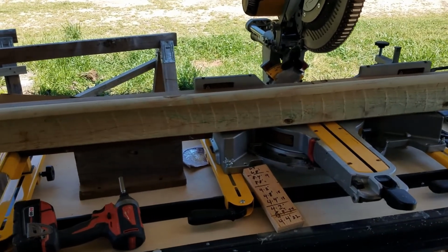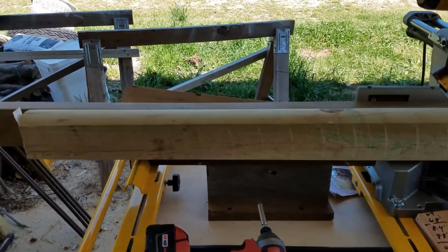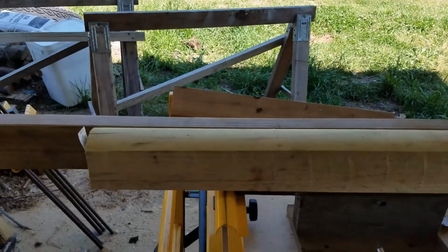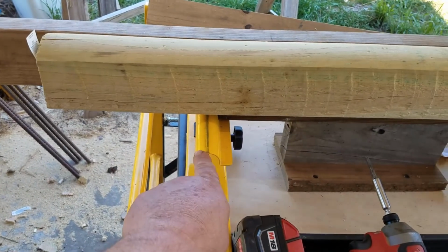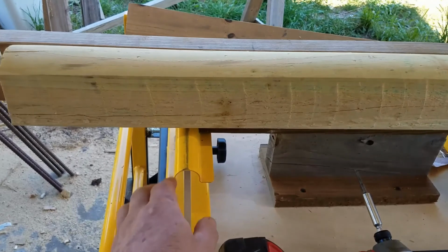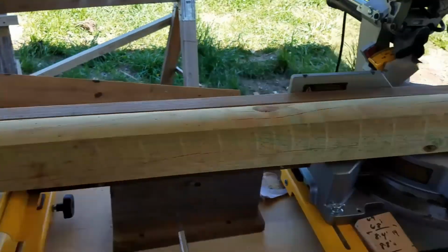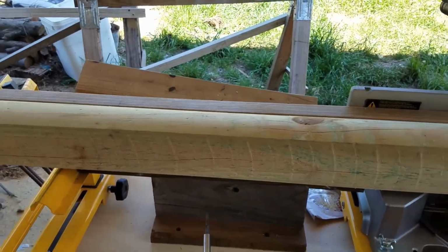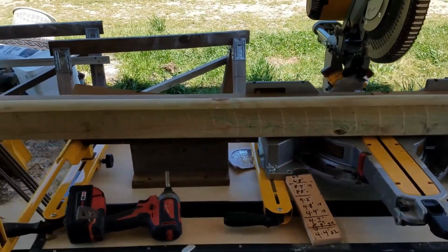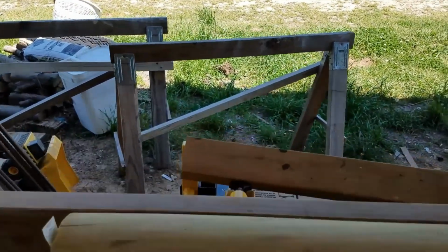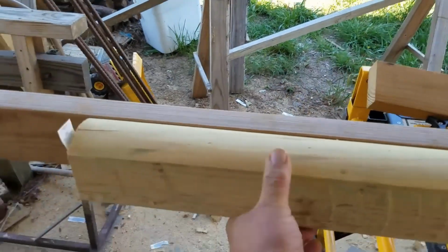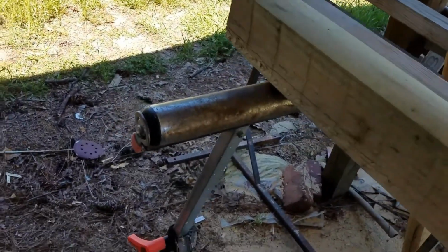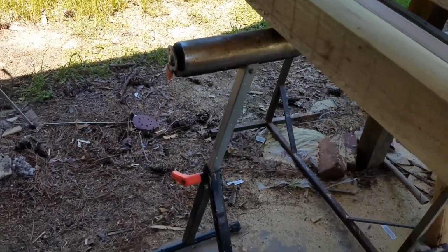When you're working with longer material, you need some type of support. You see the miter saw has these supports that are built in right here. So we've got them adjusted up to where they help support the bottom of the lumber. Got those on both ends. But when you've got a bigger piece of wood, especially something as heavy as these landscape timbers, you want some extra support. When you slide it out, it kind of gets heavy on the end. So you can have some type of roller support like this.